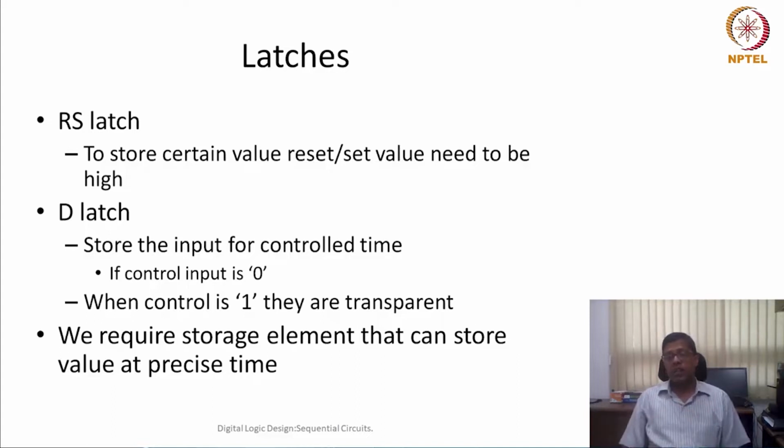Because the time when my control input is 1 gives a significant amount of time for my input to change, these latches may not be a very good component to do synchronization or to store the value for a definite amount of time.